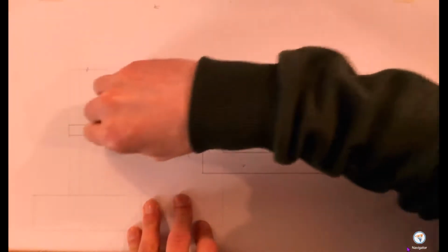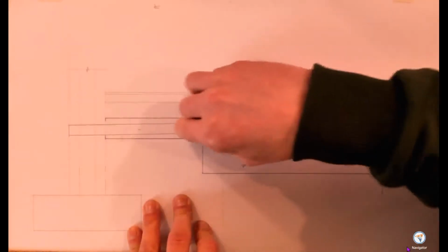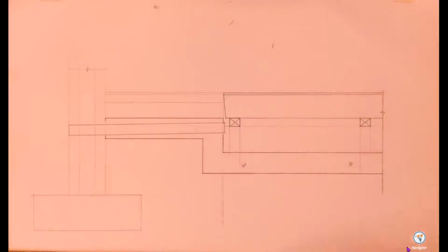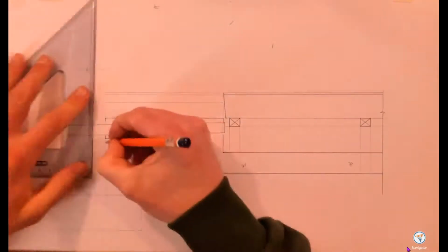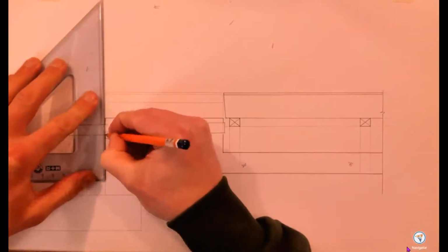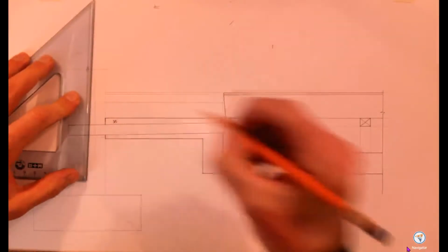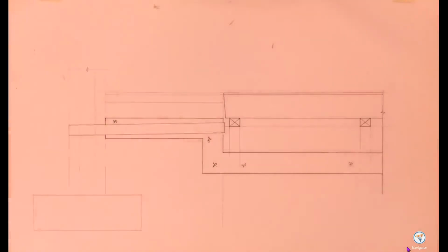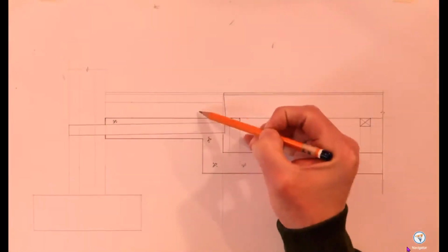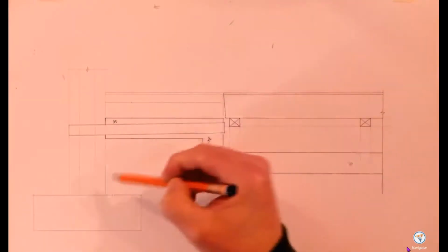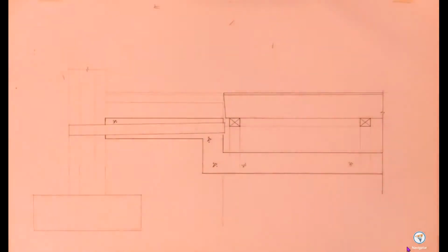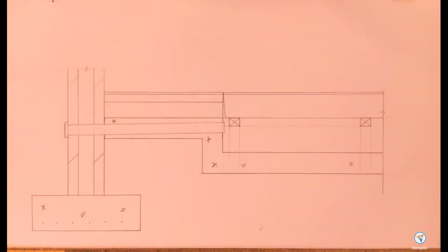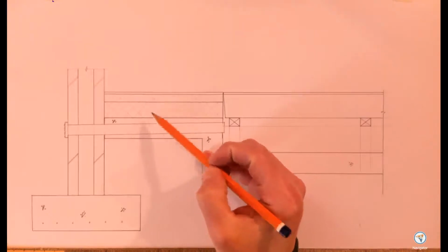Now it's unfortunate where I put my two symbols because they're right in the middle of the pipe. Get rid of those. So now I've got my subfloor in, ventilation going in through it, and here is my finished subfloor. I'll darken in the insulation, the floor, and now I can darken in all my foundation, and then we'll finish off the drawing. Okay, I've darkened in all the floor and the walls.